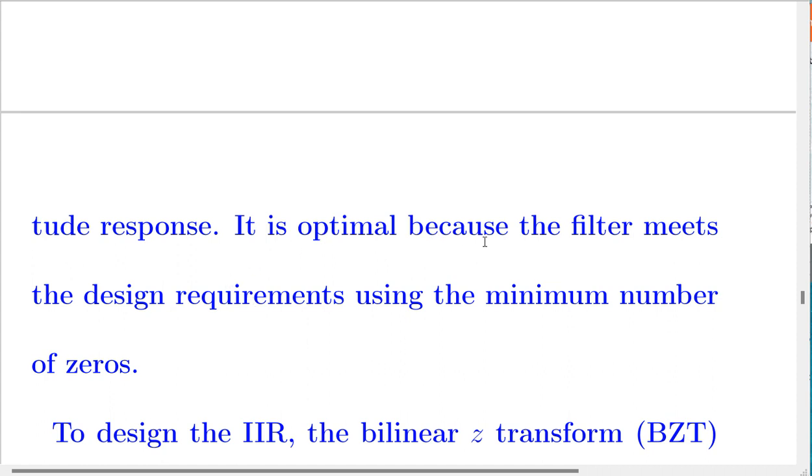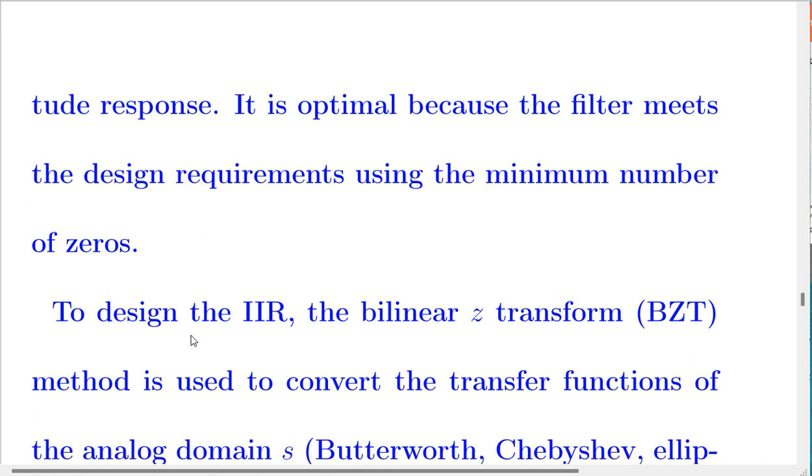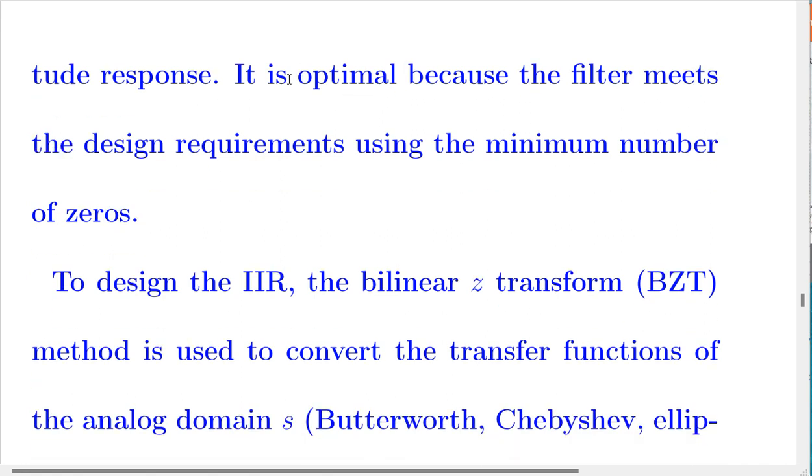It's optimal because the filter meets the design requirements using the minimum number of zeros. So the best technique for FIR design is the Parks-McClellan technique. Of course, we will discuss other types of designs as well, for example, window-based filtering for FIR. But here you see the most important technique for FIR design. Okay?